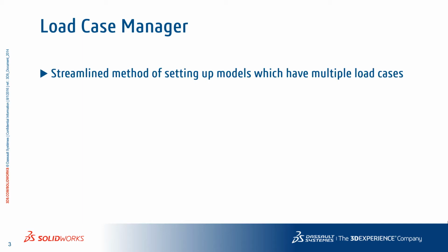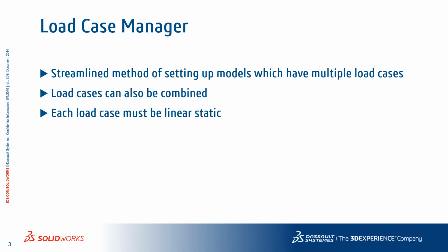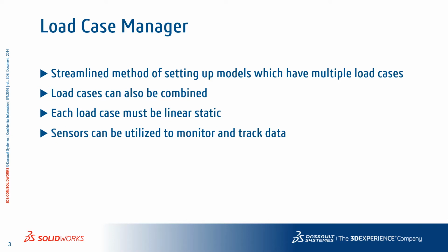Now, Load Case Manager was introduced in about 2015, I believe, and it is a streamlined method of setting up models which have multiple load cases. Now, the caveat is that the load cases need to be linear static. You can combine the load cases, so if you want to combine load case A with load case B, you just have to be aware that when you're doing those combinations, you want to make sure that you are not moving into the nonlinear realm.